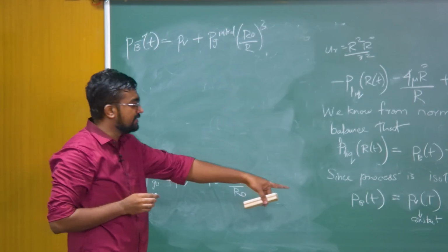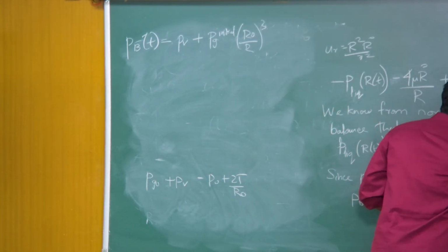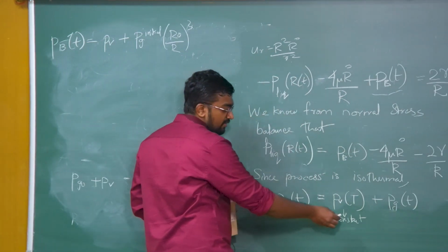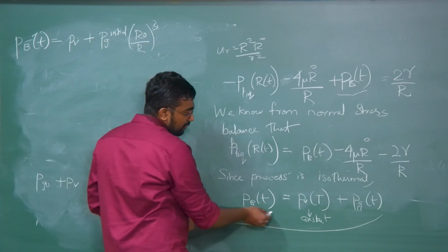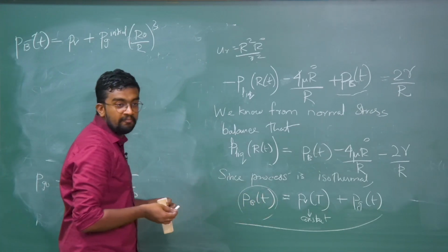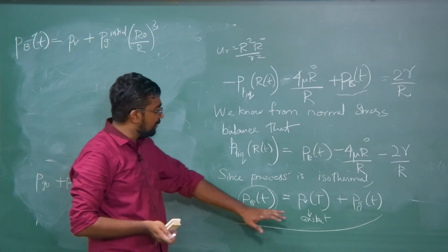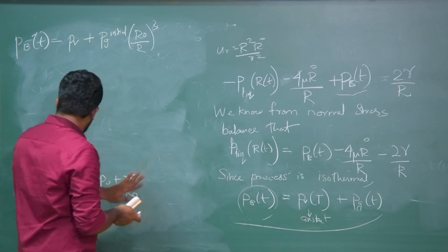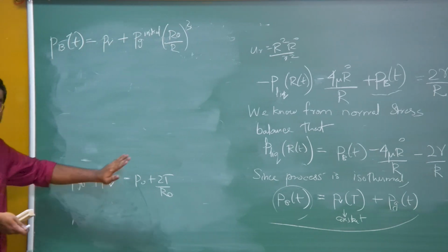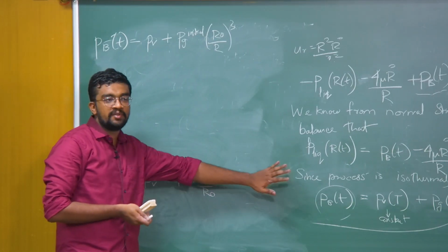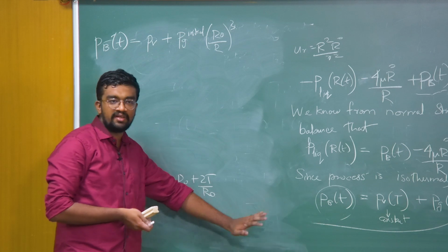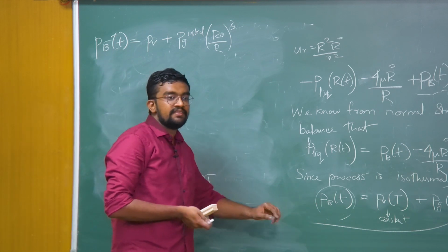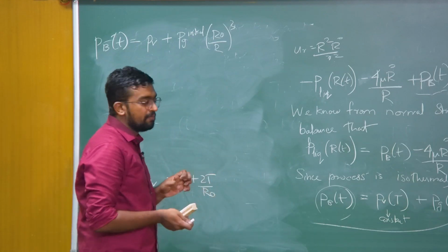I just substituted the gas pressure at any given time onto this equation to get the bubble pressure at any given time. You should know that Pv, the vapor pressure, is a constant from the initial condition to whatever condition we have, because the problem itself is isothermal. So, it is like an additional pressure inside the bubble.